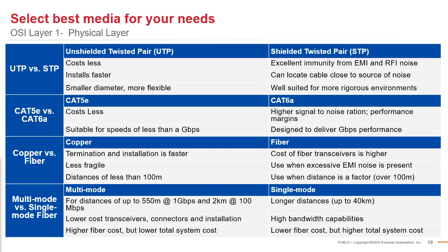So the first question we had was, when do you choose? How do you choose multimode versus single mode? If I was building a new facility, I would probably, for my infrastructure, my outer ring or whatever, put a single mode fiber backbone in there. And eat the cost of the more expensive electronics, because you're future proofing your bandwidth availability.